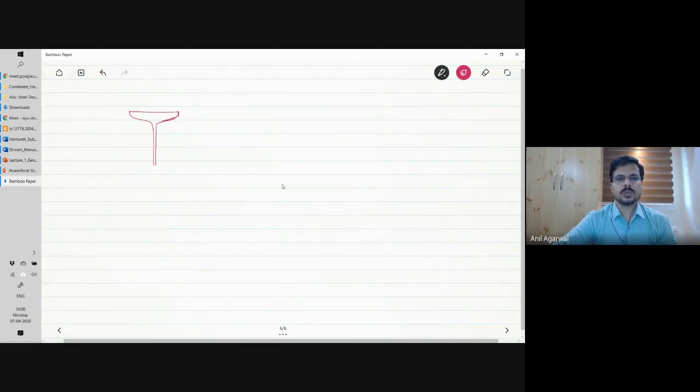So if you look at the flange width, it varies quite a bit. Of course there will be a toe in the beginning, and there will be this kind of a radius or a fillet here towards the end. But in between also there is a constant slope. And this constant slope is generated because of the rolling process. The way your rollers are designed, because this shape comes out from a rolling process, right? As I had described in the previous class. There is a roller which rotates like this, which gives this shape.